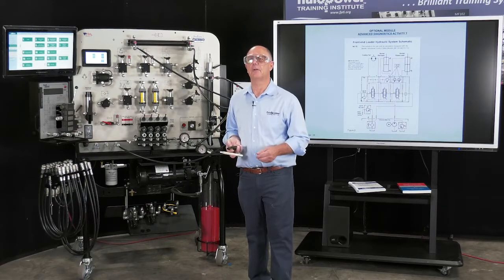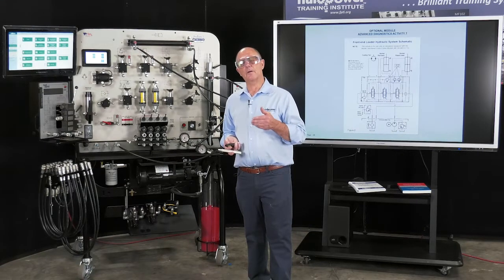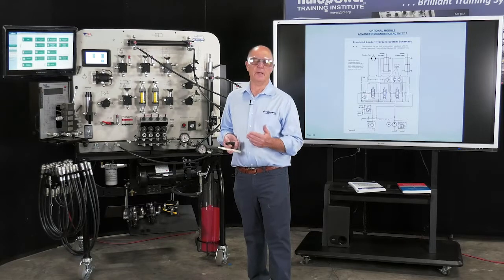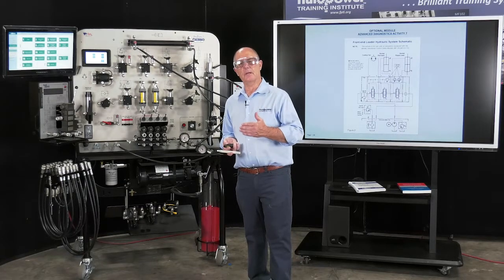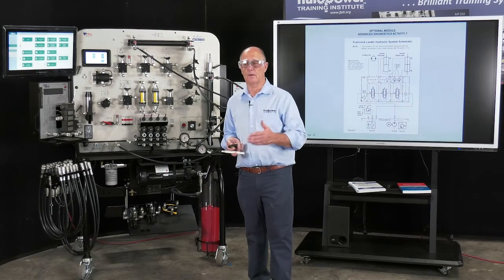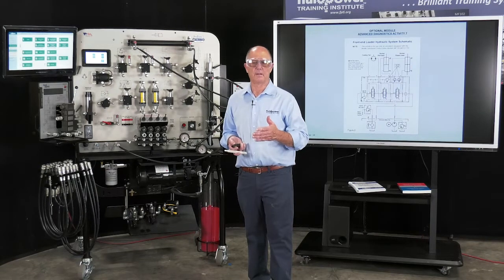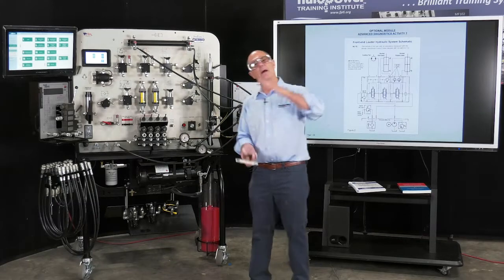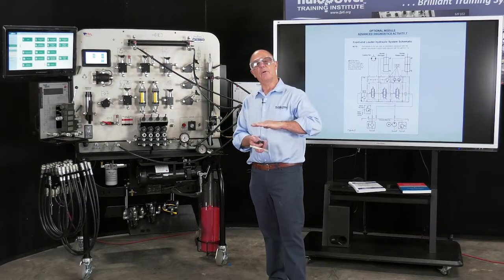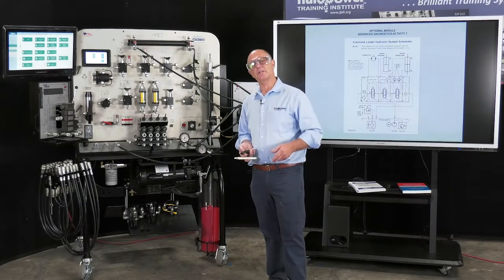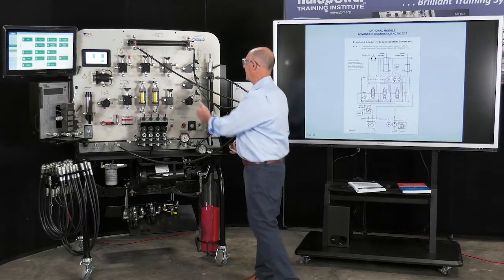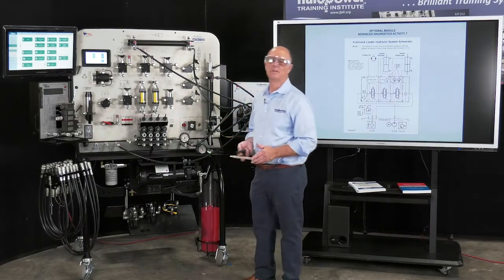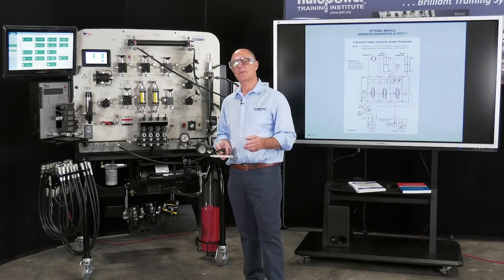a horrible amount of leakage. If you've got a 50-gallon-a-minute flow meter or a 30-gallon-a-minute flow meter, these flow meters, whether it's a turbine wheel flow meter or an analog flow meter, only start reading flow at about 3 to 5 gallons a minute. So you're off the radar screen. It's not going to work. So really, when it comes to testing these kinds of valves, directional valves, pressure control valves, etc., there's only one way to do it.